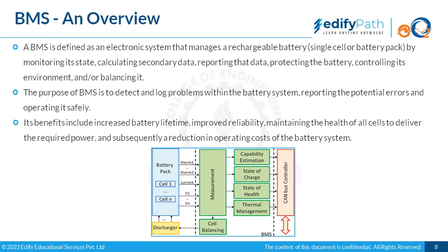Say when I'm putting my battery on charging, I don't have to remember that after 2 or 3 hours I have to remove the charger, because the BMS has been programmed so that when it reaches a particular voltage, it won't take in any more charge. This way the safety feature is maintained, and at the same time it is coordinating and managing these number of cells so that the battery functions as a unit.